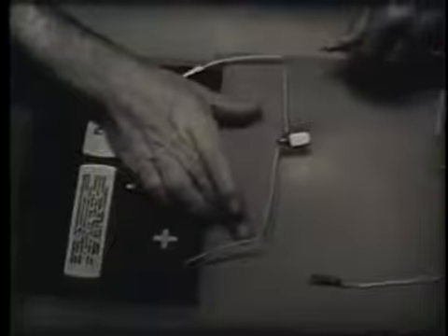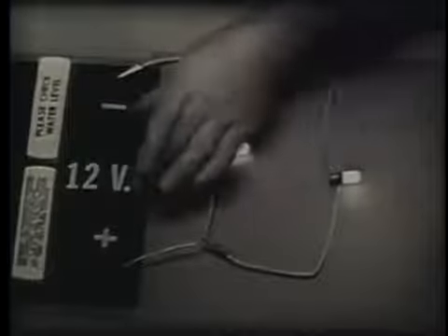Now, since the applied voltage is felt across this bulb, I should be able to connect this one like this and still have the applied voltage across it. And you can see that it's starting to look like a parallel circuit. Now, we could add a third branch, a fourth branch, and on and on. Each branch would still have the total applied voltage.